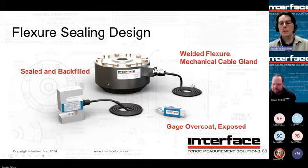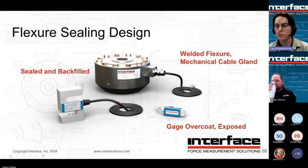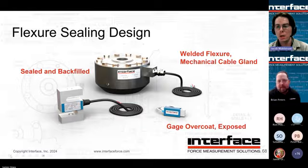Alrighty. So sealing considerations, right? This is directly related to the application and the environment the load cell is going to be used in. You can see there in the middle, we have a welded, kind of hermetically sealed 3200. And so we got the welded diaphragm. That's going to be top and bottom, as well as a welded, we call them a doghouse, where we put a lot of the tabs and perhaps an amplifier. And then we have a cable gland coming out here with the cable.